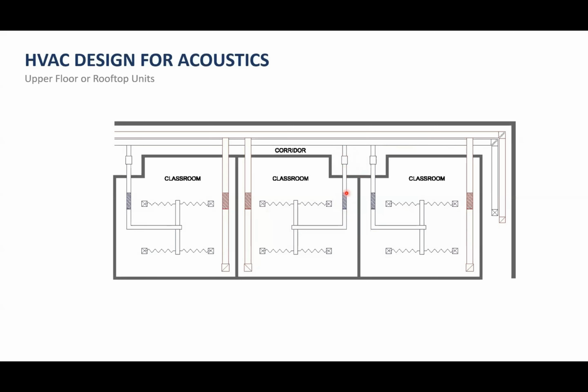You may need a silencer after the VAV because they can still add more sound right there. And so now you had a lot of duct length to take care of the sound from the main unit, but now you do need to reduce some from those VAVs. Some manufacturers have them integrated, and so those are options. But again, we still have otherwise fully ducted return. We've got flex duct here.